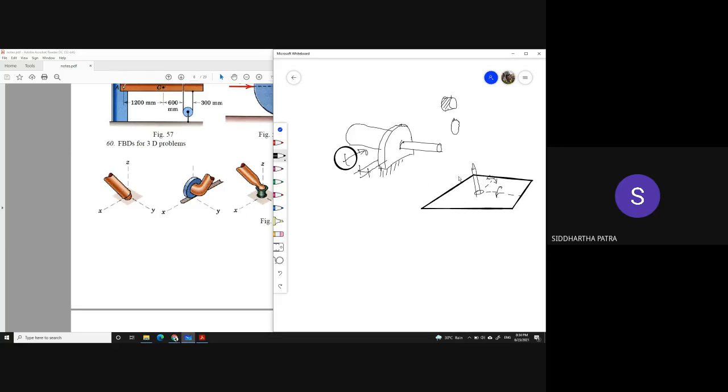Okay, so in that situation, you can actually perform a little bit of tilting of this shaft. Okay, in either of these two axes, this one or this one, and that little bit of tilting, although it's not completely free to have any arbitrary amount of rotation, is not as good as fixing those degrees of freedom, and therefore in that situation you can think of those moments as not acting.